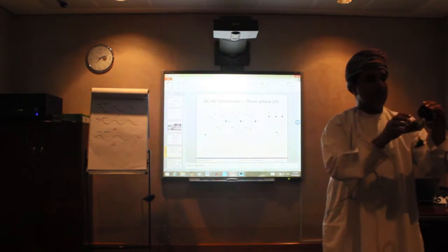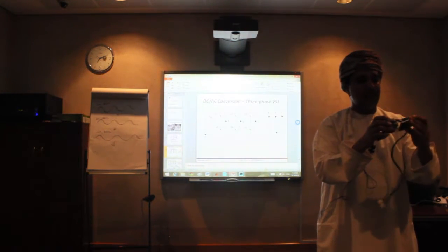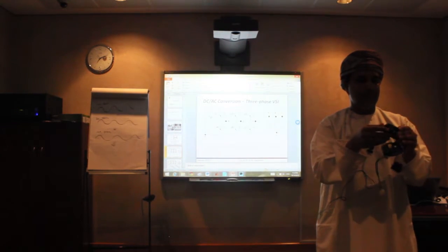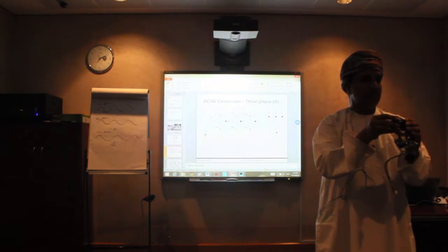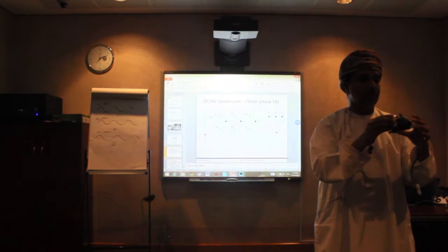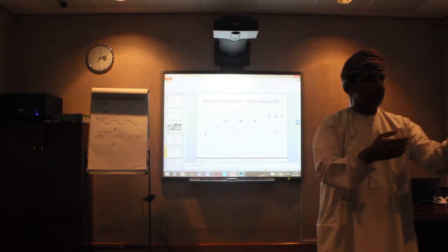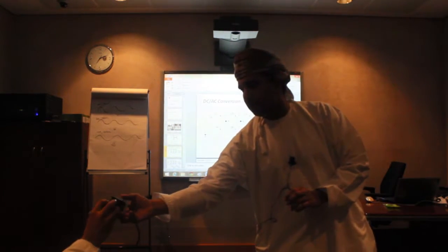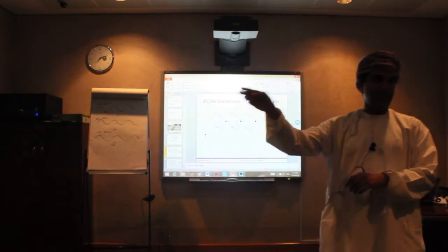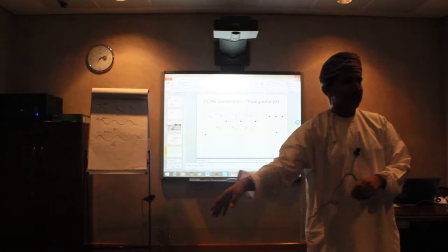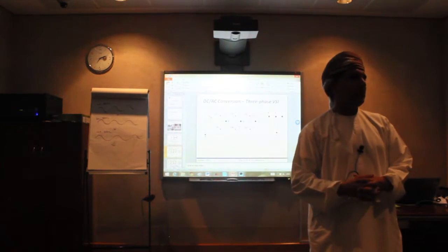And in addition to that, for the heat, you can see that there is a fan here for the cooling system, right, to cool the components of this inverter. By the way, it has a filter, everything. You see that there is a capacitor with an inductor and everything there to filter the harmonic components.